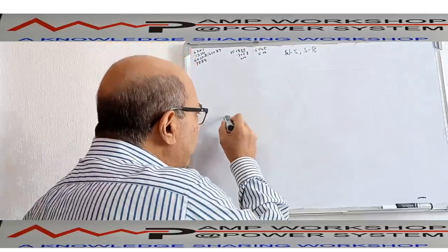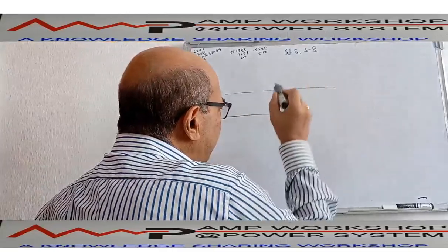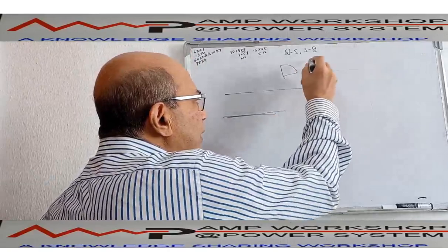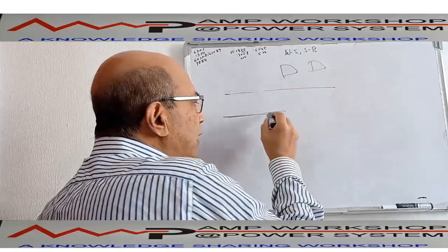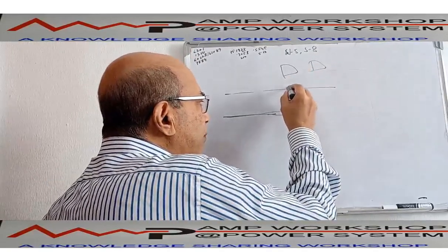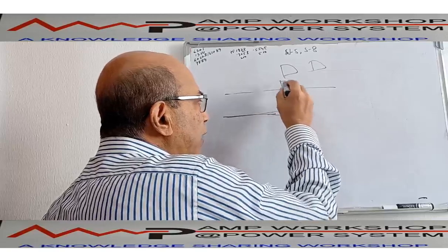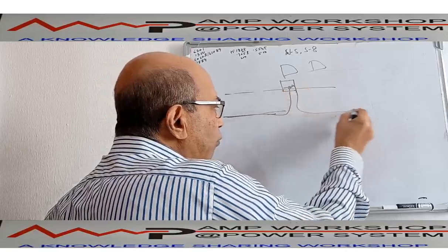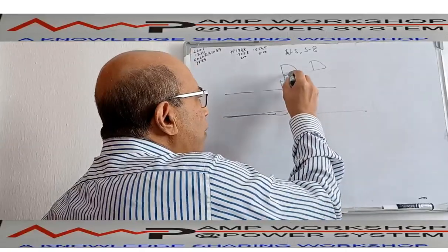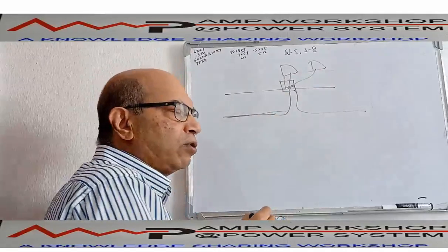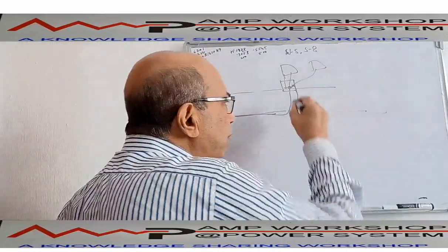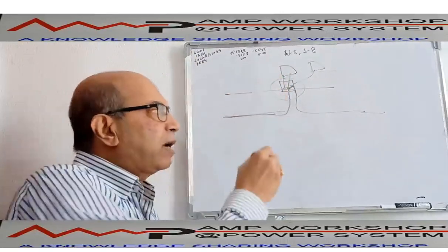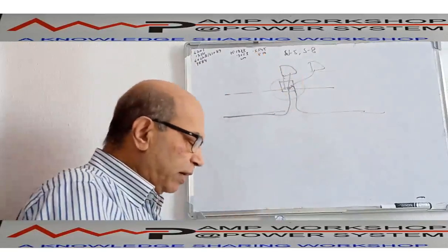If you take an underground cable, suppose this is the ground level and the cable is going through it. If you want to distribute power, suppose there are 3 houses over here, then you have to bring this underground cable to the surface. You have to put a splitter box or a junction box, where the inlet cable will be connected, and then it is a tee-off, and it will continue again, and the tee-off supply will be given to these consumers. Similarly, again it will go on. So every time this type of arrangement should be there, with the distribution box, with the breaker or some fuse.